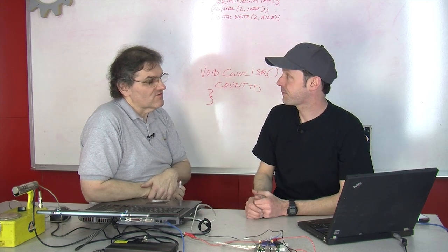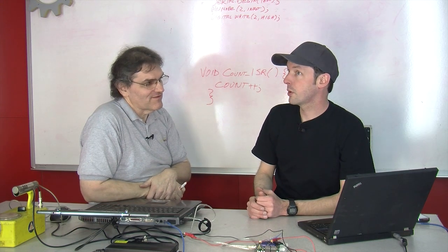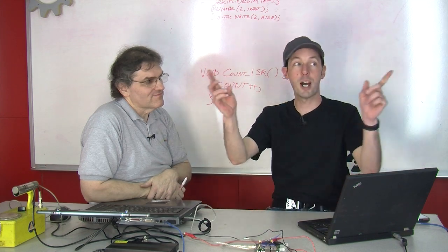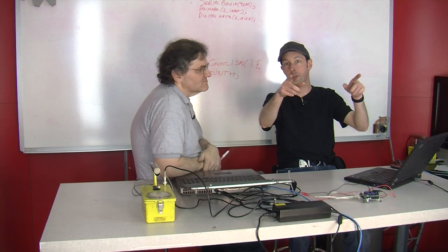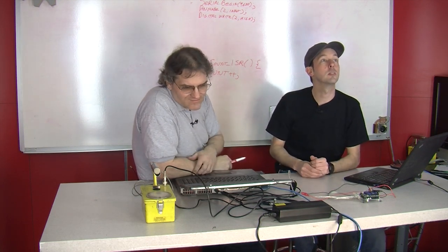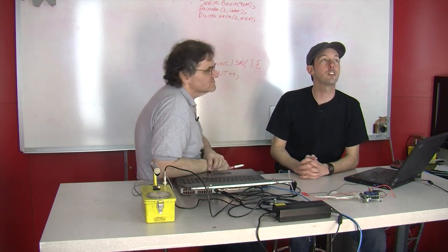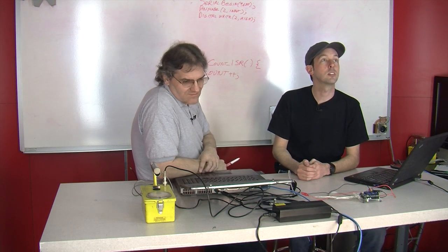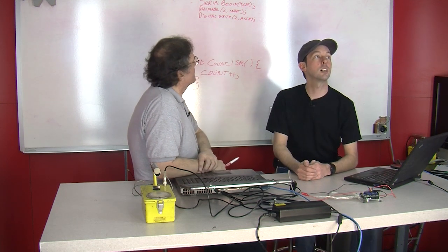You have additional outputs on the cameras that you could parallel that? If we can't pull it right off the camera, I know we can pull them off the monitors that the cameras are feeding, because the cameras feed the blocking monitors, so we could do that. I was going to have to put a Y in the cable that's coming out from the camera. You could get impedance issues doing that, but I'm sure we can get the loop outs from the cameras. The only thing... I was going to say, nobody can just save it and stream it live like we were doing the editing. Yeah, we could be doing that.